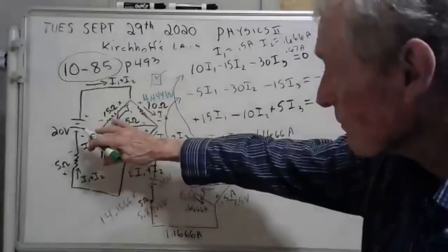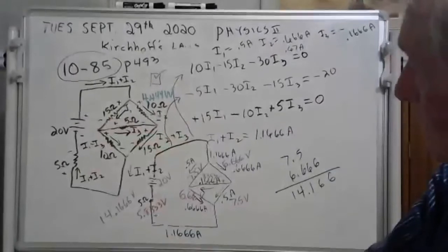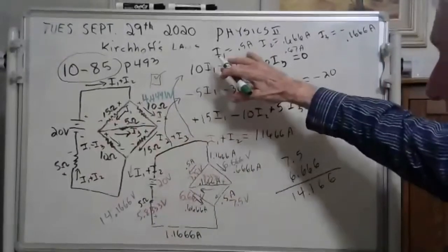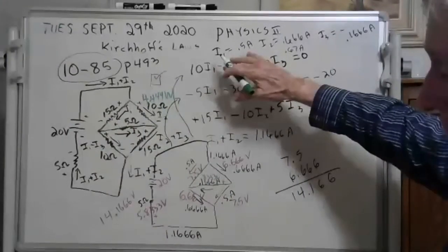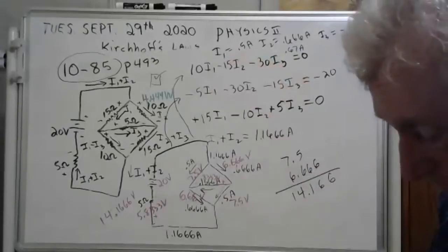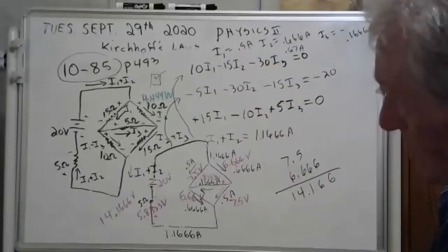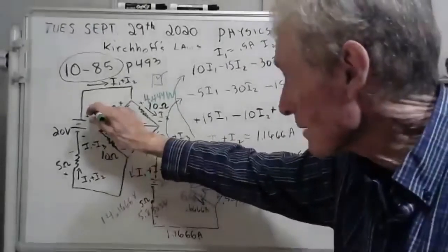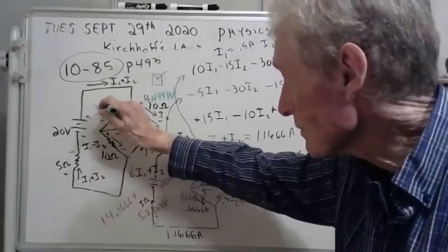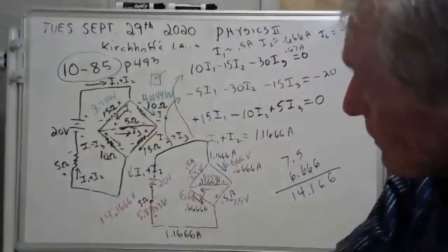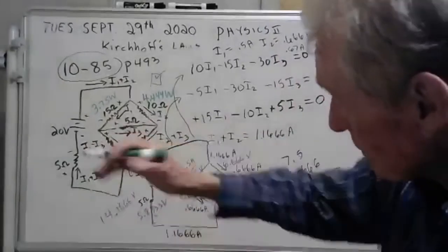Now let me do this one. I don't care which equation you use, but I could just go the current, which is 1/2 amp. I could go I squared R, that would work. What is 1/2 amp squared times 15 ohms? Well, here's what I'm getting. 3.75 watts on that one.